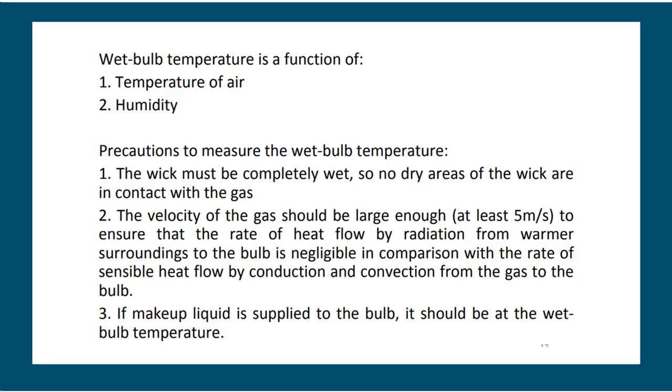Okay, so if you consider a drop of water at the tip of a thin wire, and if the temperature of the water drop decreases with time, what will happen to the vapor pressure? The vapor pressure will decrease and it will cause a reduction in partial pressure driving force. So the temperature driving force for heat transfer from ambient air to the water will obviously increase, right? If sufficient time is allowed, a steady state temperature will be attained by this water drop, and this temperature is called the wet bulb temperature.